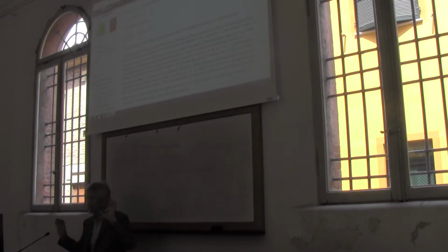Of course, this is a tricky step. Identification of what are the physical parameters governing the process is a tricky step. If you forget something, your dimensionless analysis is not complete. And there is some subjectivity. For instance, you may decide that hydrodynamic force is not relevant, and therefore you forget one, which is V. So it depends on your evaluation of the process, your technical evaluation. You don't have to forget anything if you want to move forward in this way.